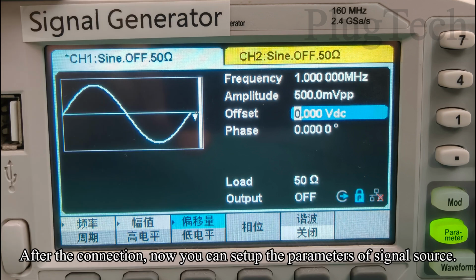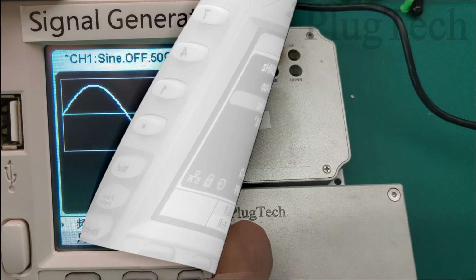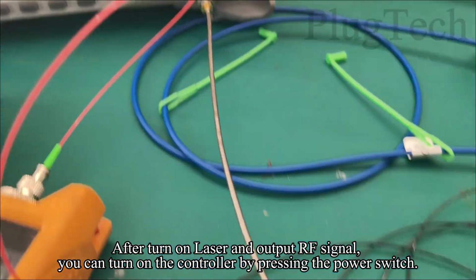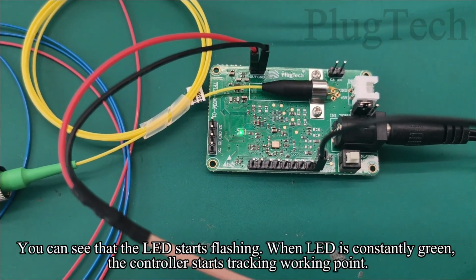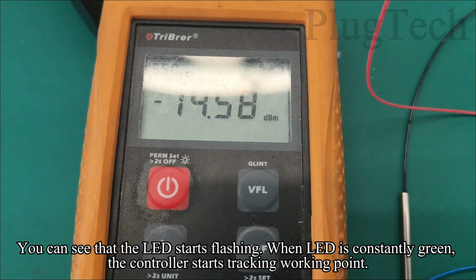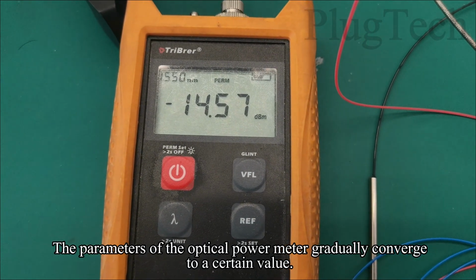After the connection, now you can set up the parameters of the signal source. In this case, we will apply a sine wave with a 1 MHz frequency and 0.5 volts VPP amplitude. After turning on the laser and outputting the RF signal, you can turn on the controller by pressing the power switch. You can see that the LED starts flashing. When the LED is constantly green, the controller starts tracking working points. The parameters of the optical power meter gradually converge to a certain value.